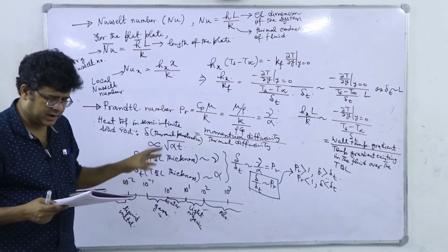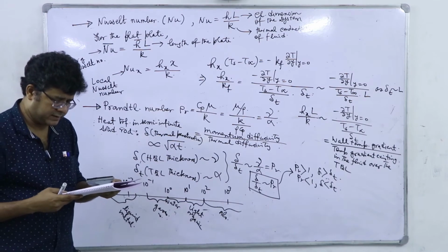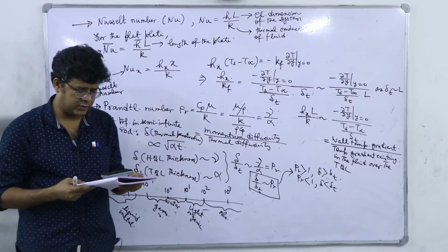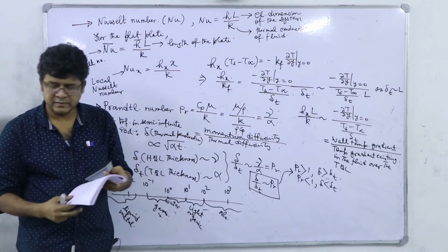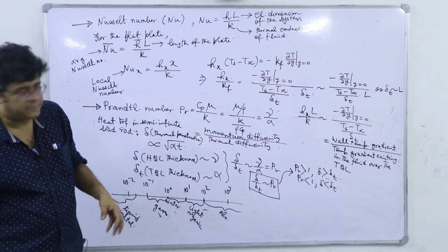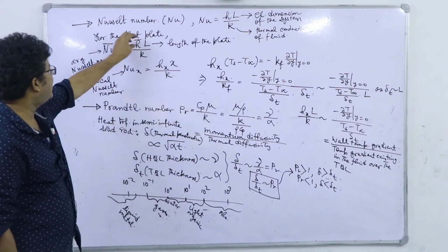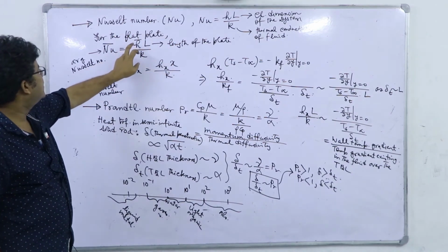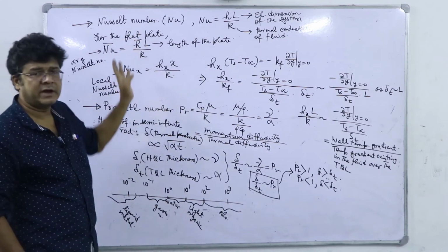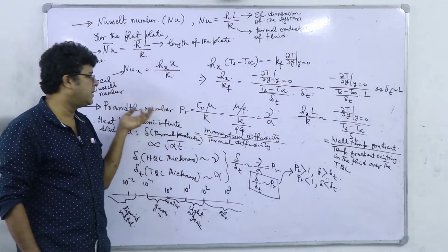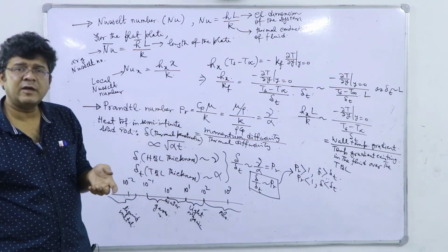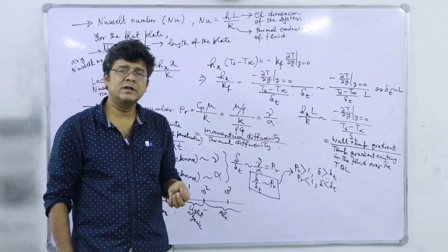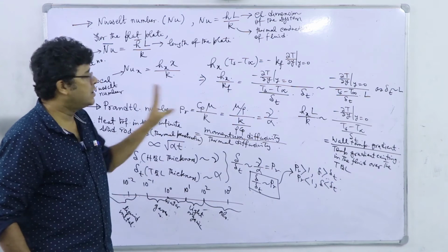Now, for air, the Prandtl number is 0.7, right. 7 for water at room temperature, oils have very high Prandtl number, liquid metal has got very low Prandtl number. So, this variation is because of the difference in temperature. So, first we have discussed the representation of this heat transfer coefficient in the dimensionless form, that is Nusselt number, the ratio of the diffusivity in terms of the Prandtl number, and the third one, as I have mentioned, the velocity. I am not discussing it. So, definitely you can understand that it will be the Reynolds number, right? Reynolds number definition is very well known, so I am not going into that.